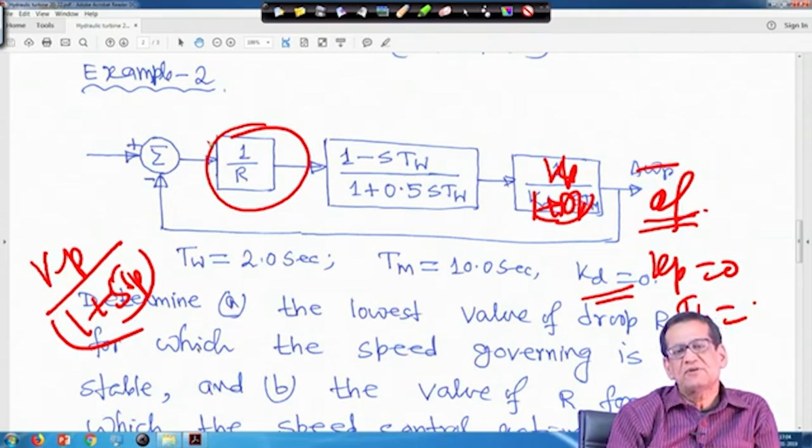Whereas in the case of a hydro turbine it is not like that, right. And it is a very high value, right. A typical value is 360 percent per minute for raising the generation, and for lowering the generation it is 270% per minute. It is so high that the generation rate constant GRC for a hydro turbine does not have any effect on the dynamic responses, but the governor time constant for a hydro turbine is different and larger than the steam turbine governor time constant.